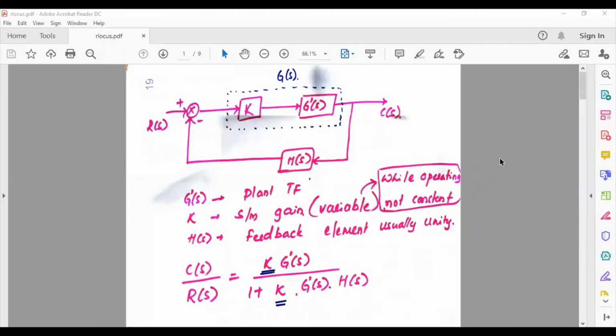Okay, see, now imagine a car as a plant. Sahu, answer me parallelly. Yes, sir. You imagine a car. Okay, a car is a system. It is as good as a mass block, you can imagine, right? Mass, spring, damper. So if you model it, suppose imagine 1 divided by ms square plus bs plus k. That is the transfer function.